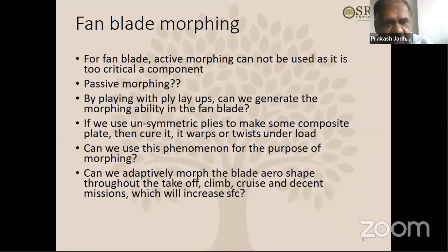Okay. So basically this composite blade is made of laminates, a layer by layer structure. And basically what we do is we buy this carbon fiber epoxy prepregs, and we hand lay up in the mold shape, and then we cure it. Cure it using an autoclave. That's how it is made.